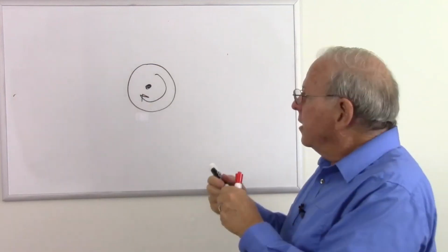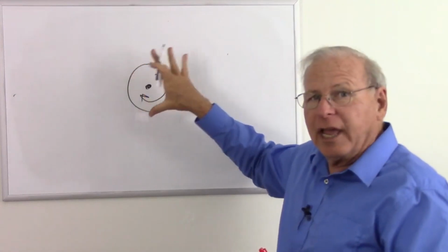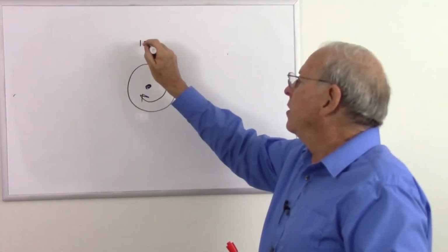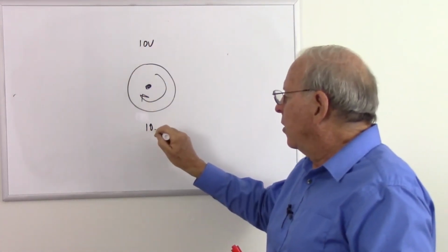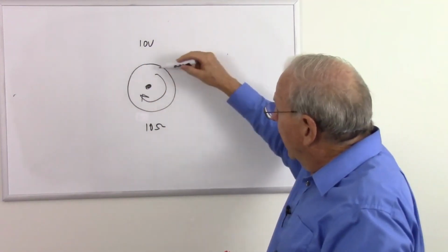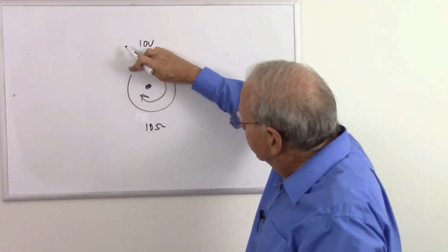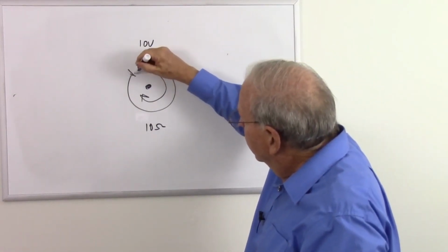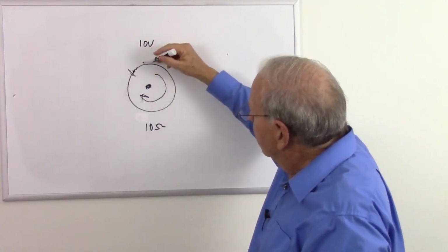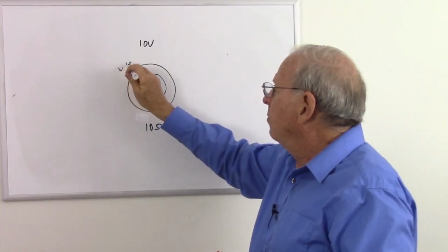0 volts. Why? Because to analyze this, we have to break it up into its voltage and its resistance. 10 volts, 10 ohms, and we have to put those in series with each other. To fully understand why I measure 0 volts no matter where I put it, I simply broke this into 10 pieces. I'll just draw one here. 1 battery, 1 resistor, and we have 10 of those around there. Each is 1 volt and 1 ohm.